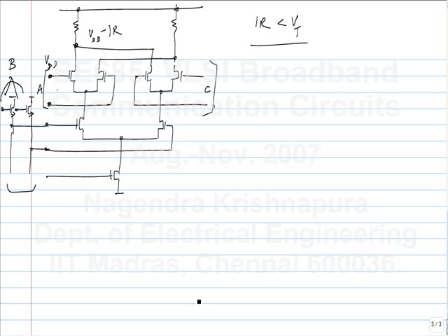Any questions? So we have a multiplexer which realizes this, and one of the things that we needed for our serializer was the multiplexer. In fact, the serializer was built around the multiplexer, and you can use this circuit to do that at high speeds. At very low speeds, of course, you can use CMOS gates. And the key here is every signal is differential, like all three inputs and the output, and also the current through the supply and ground is a constant.